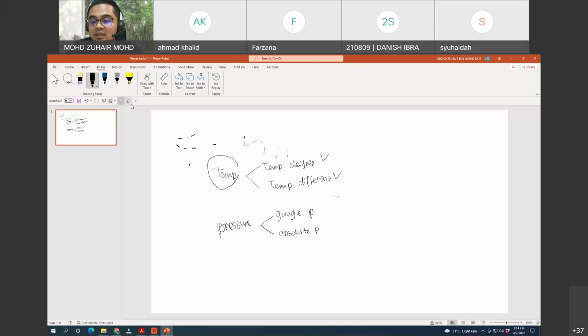For instance, we normally refer to pressure on the gauge, where the needle will show the pressure. This has nothing to do with absolute pressure, as no atmospheric pressure interferes in the reading of the gauge. That's why we call it gauge pressure or relative pressure.